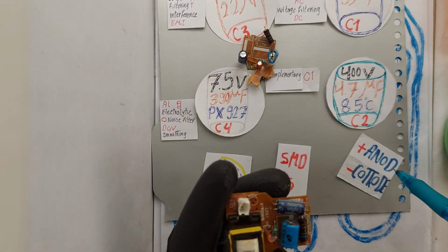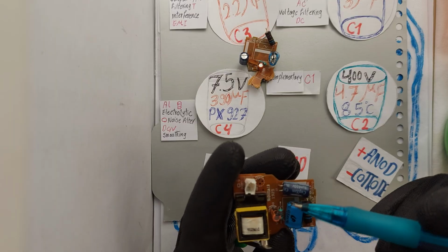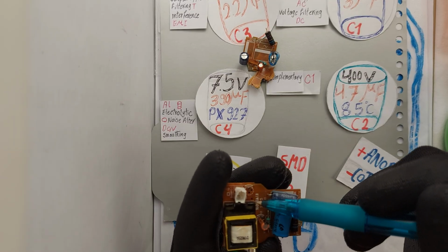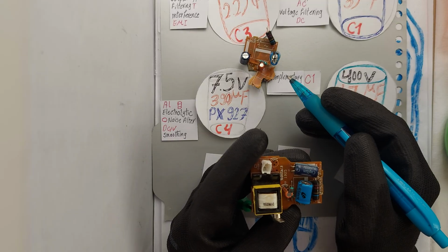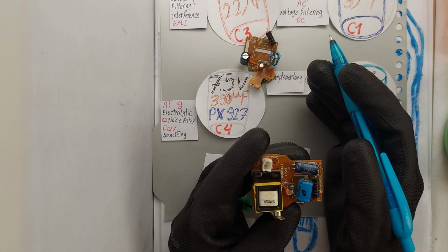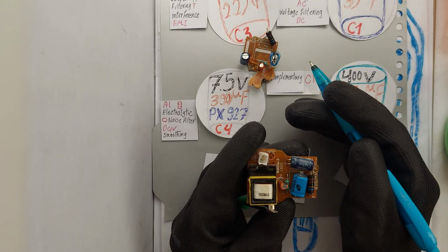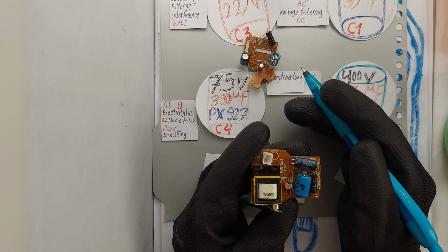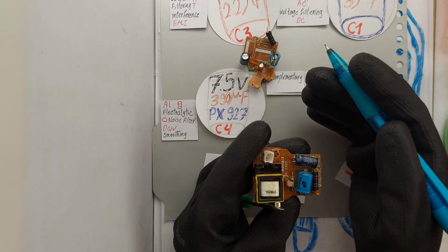as you can see here, while C3 and C4 are circles. The difference relates to the capacitor type and schematic drawing standards. C1 and C2 are polar electrolytic capacitors operating at high voltage, around 400 volt.